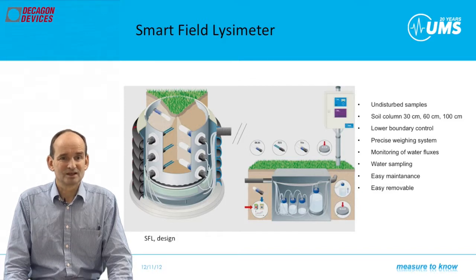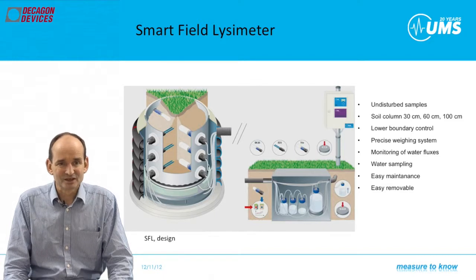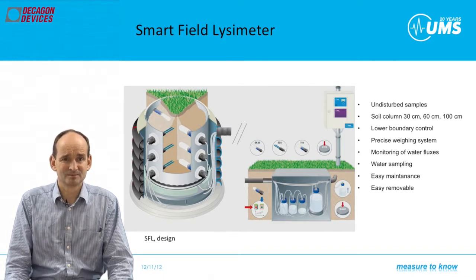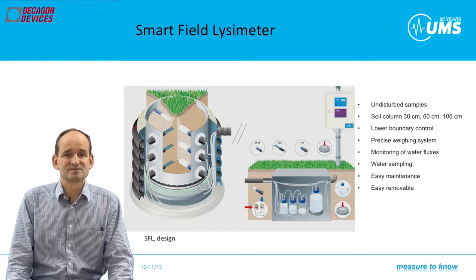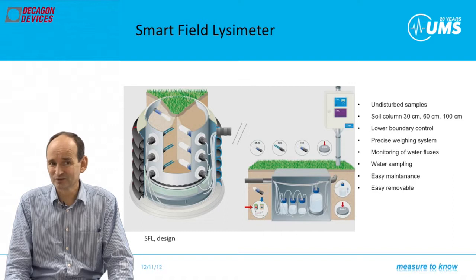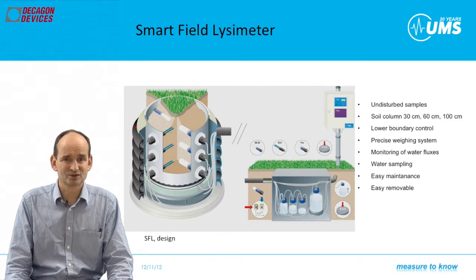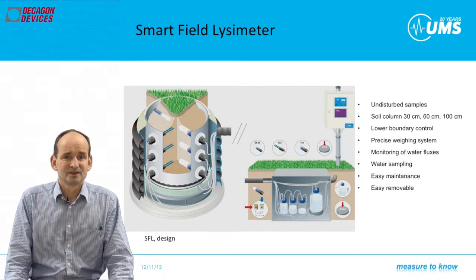So you install all lysimeter soil probes and the balance to 1 unit before you let it down into the lysimeter enclosure. The lysimeter enclosure has a steel barrel body that gives best thermal response to the surrounding soil. Its diameter is only about 450 millimeters, and a special shape epoxy collar with sealing to the barrel closes the enclosure on the top. It has a self-releasing sealing lip to the lysimeter for a minimum of influence on the measurement.